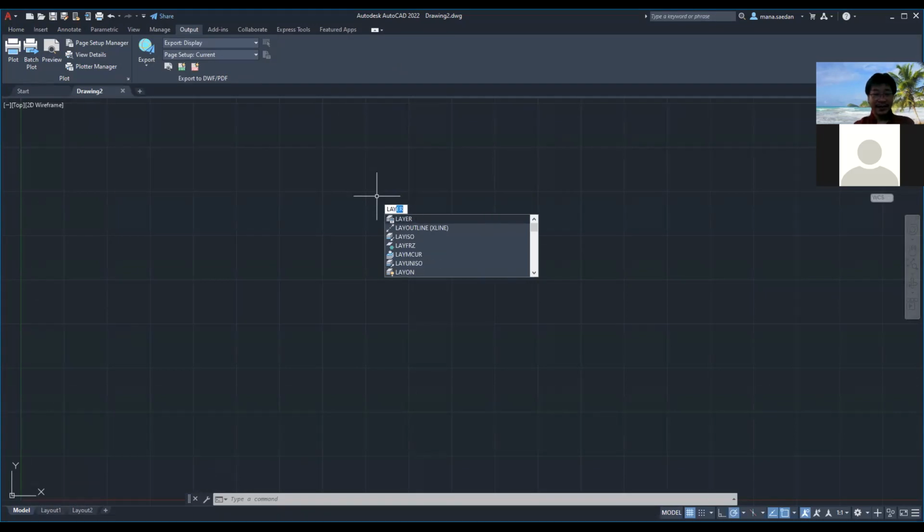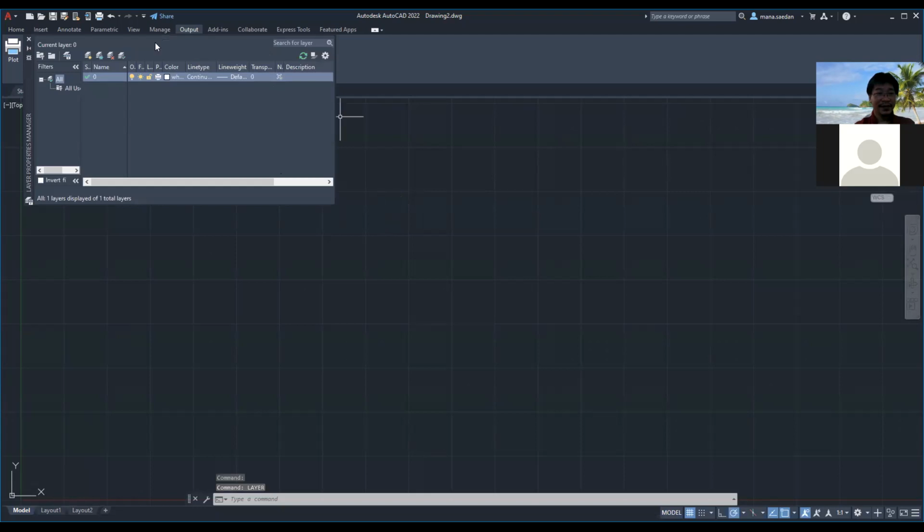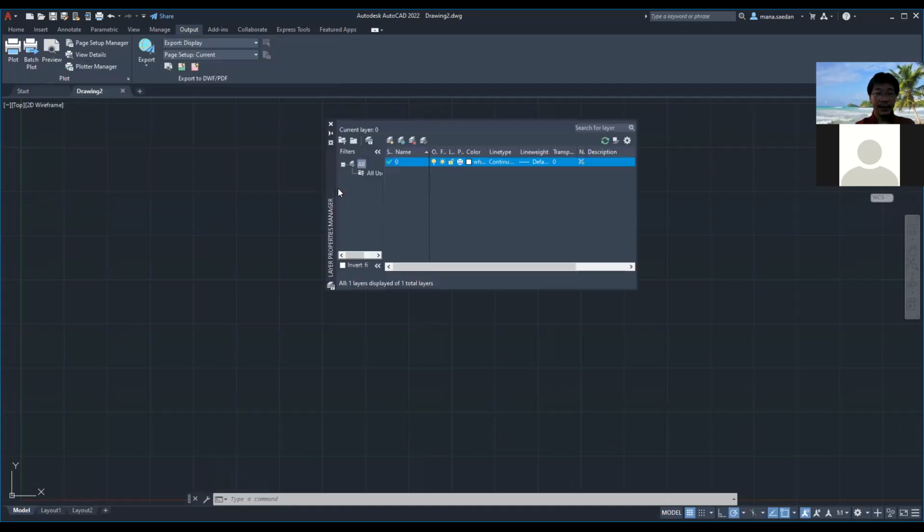All right. Okay. I just need to type it in. All right. So I type it in. The command is layer. In AutoCAD, you can use commands by typing as well, and then I create a new layer here. Okay. By default, there is one layer, which always starts for you.